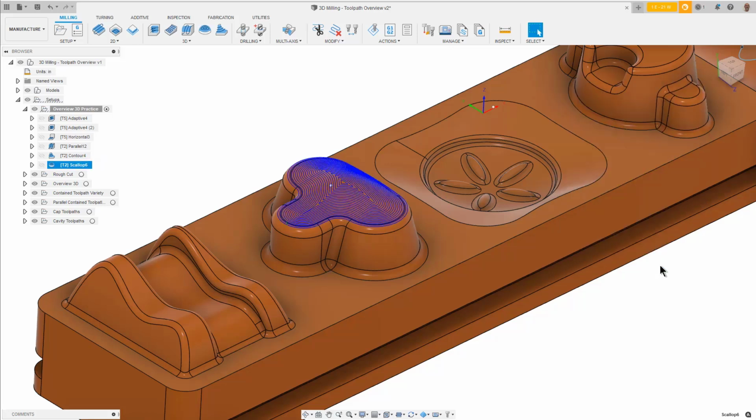That creates a nice toolpath on the top that cuts from the outside of the boundary to the inside. We could have also used that on the entire part. It would have done a good job on the vertical walls. Next, I want to apply a parallel cut over the same area.